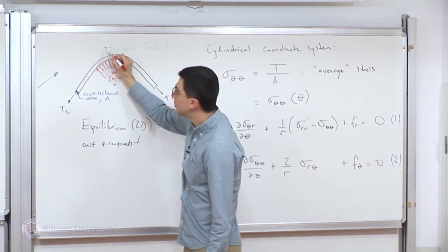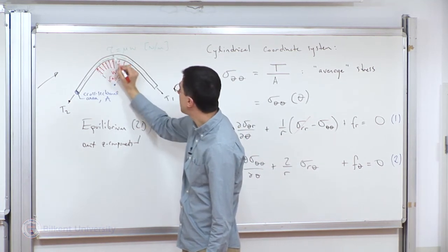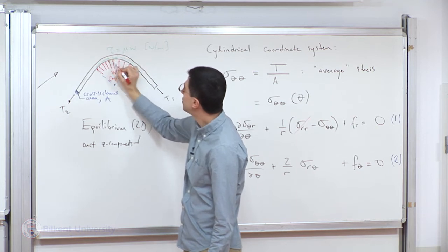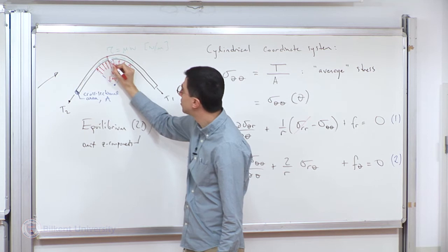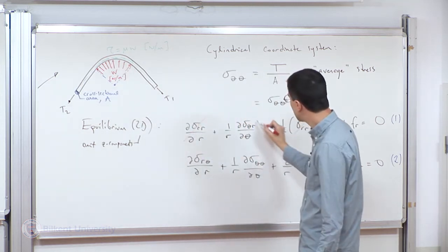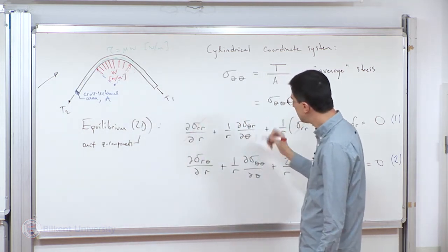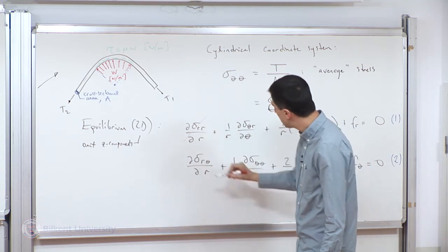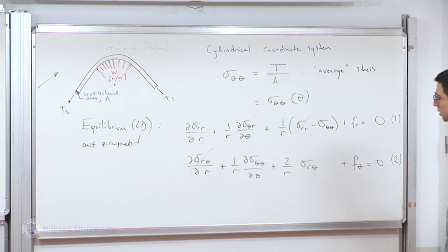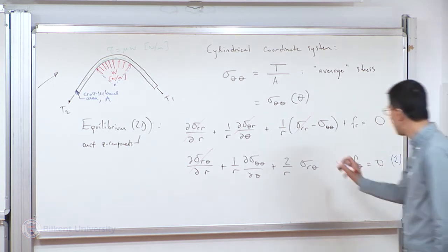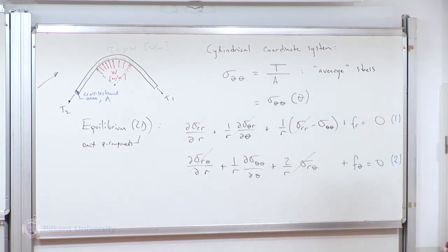Sigma on the plane with normal R in the direction theta. It has to do with the traction distribution due to friction. Here it's non-zero. Here it's 0. For sure, this thing is non-zero, right? And there is a variation in the radial direction, but I'm going to omit it because I'm going to eventually argue or hope that its magnitude is negligible.